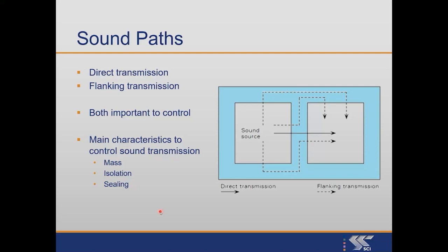And some of the main ways in which acoustic insulation is provided, well, the first one is by providing mass to separating elements and the rest of the construction. So if you've got a thick, heavy construction, then sound finds that very difficult, or that performs very well at insulating sound. Something else which enables good sound insulation is actually the isolation of separate layers.